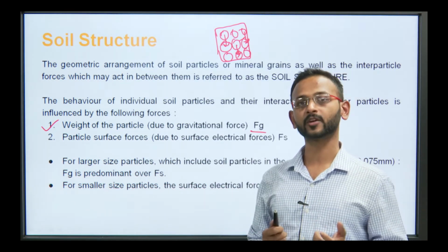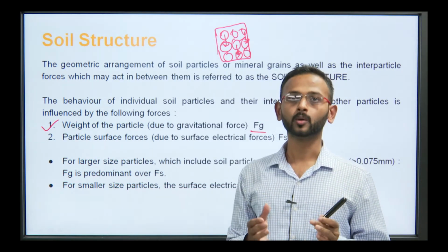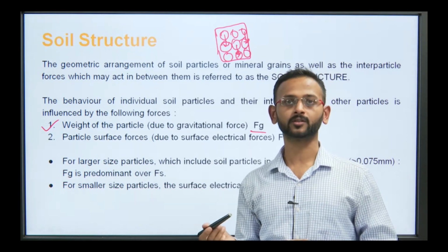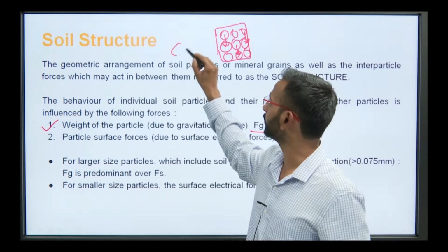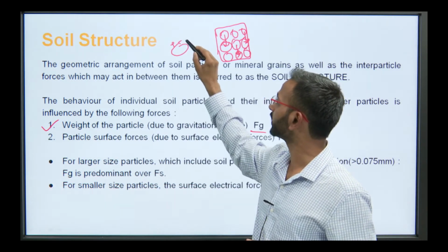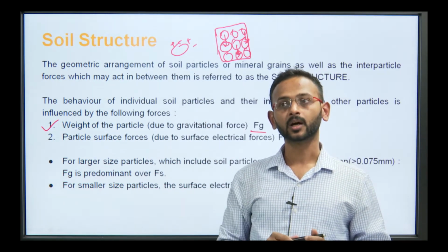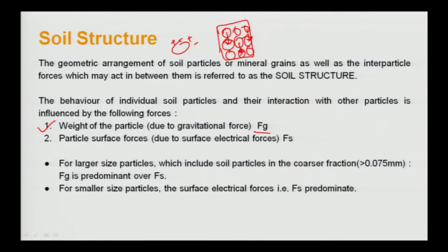Next is the particle surface forces. Each and every particle will have some surface forces, but the most predominant ones are the surface electrical charges, the positive or negative signs. A clay mineral will have some charges, either plus or minus or both. These surface electrical charges are in a way affecting the interparticle forces.